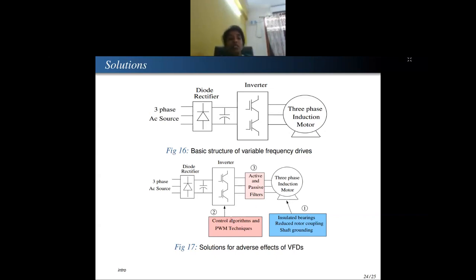And if you notice carefully, this common mode voltage is also called zero sequence voltage for this system, star and delta connected system. So what is zero sequence voltage? You could have studied it in the symmetrical component theory. So you can use that as also a control input. Until now, we could have done more of VD, VQ control, and you include zero sequence control also. That is the other option. You can control the zero sequence voltage. In turn, it will have a lesser impact on the load.